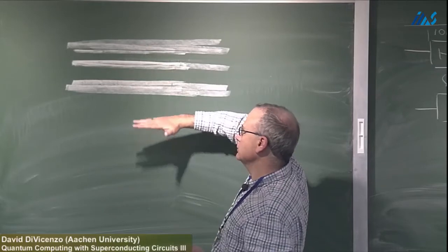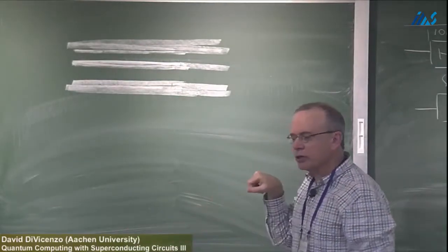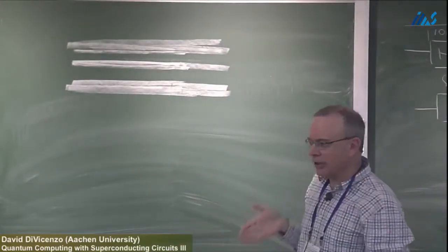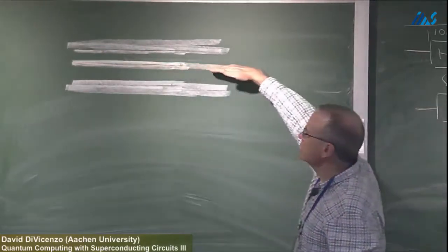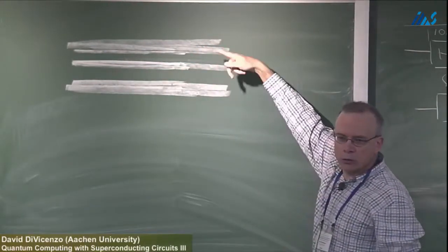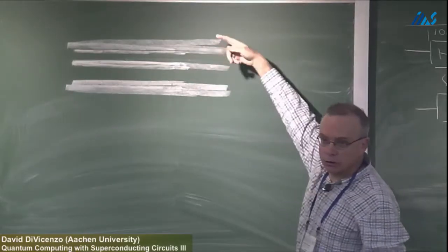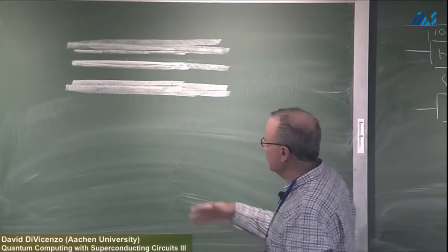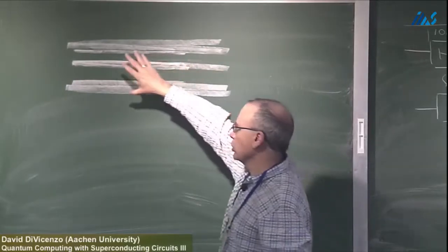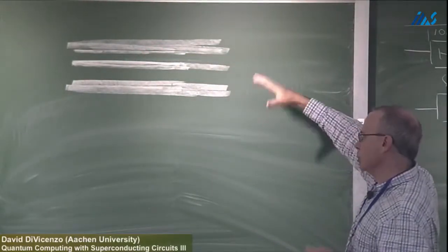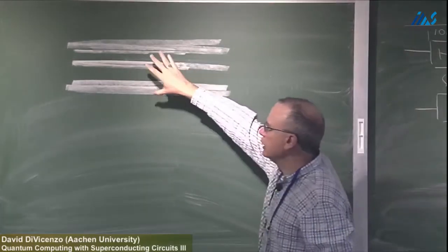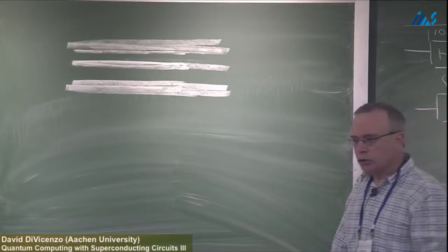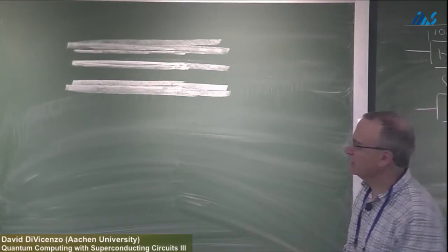So this is, well, a few things to say about this. This is a transmission line. So if you took a regular coaxial cable and you cut it in half and you looked at the profile of the metal, that's what it would look like if you did the cutting carefully enough, because it has an inner conductor and then a circular region or an annular region without anything, and then a shield, an outer shield of conductor. So this is a transmission line, and it can work. Actually, transmission lines of this form are intrinsically broadband, so they'll carry radiation at almost any frequency, but it's chosen so that it will very conveniently carry radiation in this range of frequencies that I've been talking about, some number of gigahertz. Just more or less like your coaxes for your television carry.